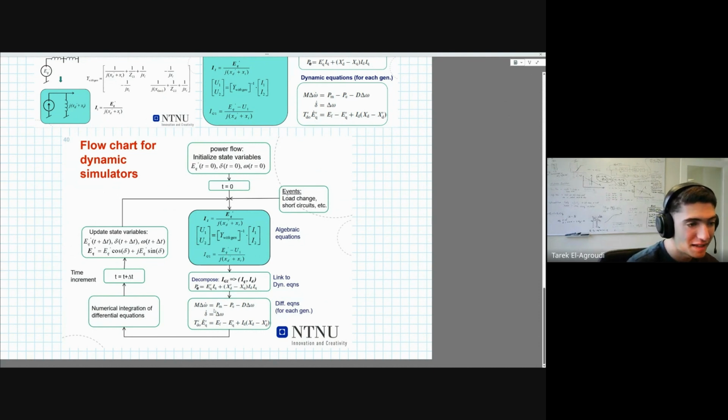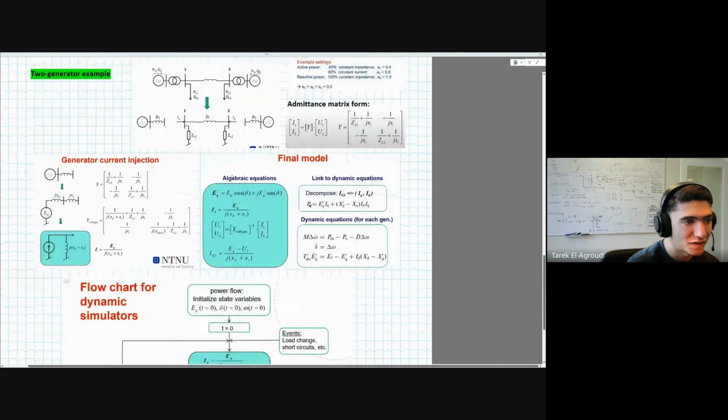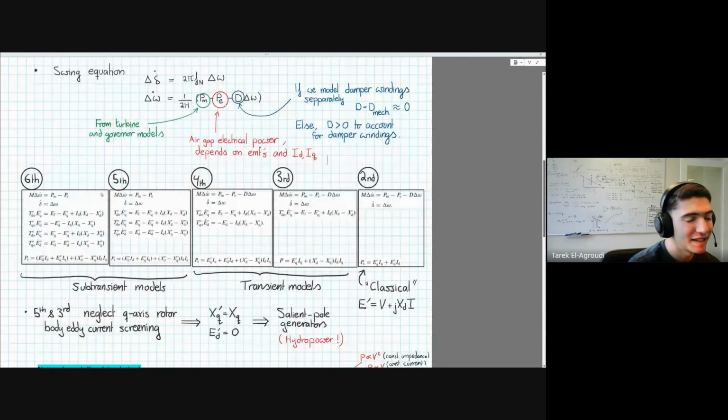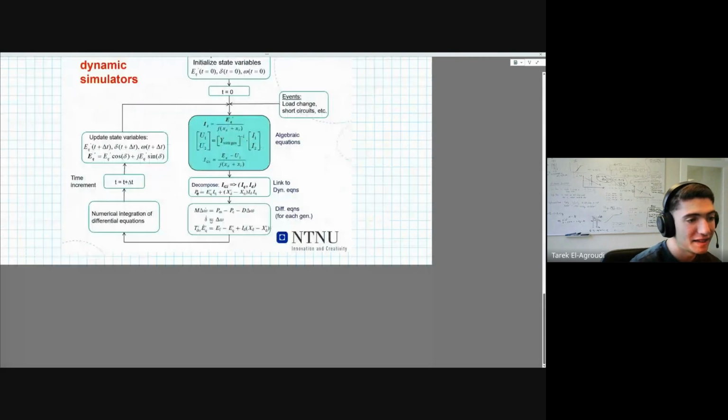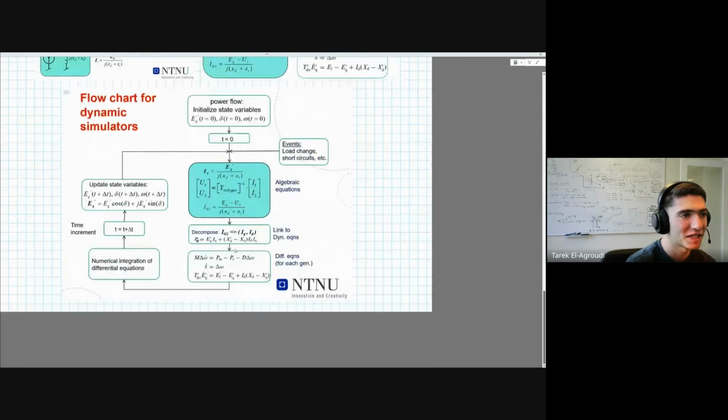However, once you have done that, you have some currents going from your generator terminals, and this current can be decomposed into a certain coordinate system which rotates, and the offset of this coordinate system is defined by this power angle. And then you can just step this model you have in a loop. So that's how you do the simulation.